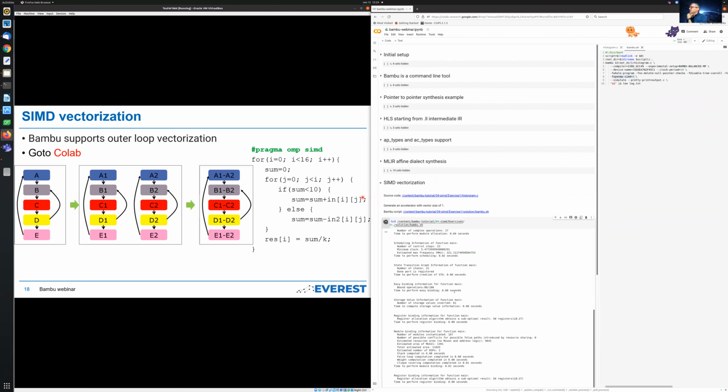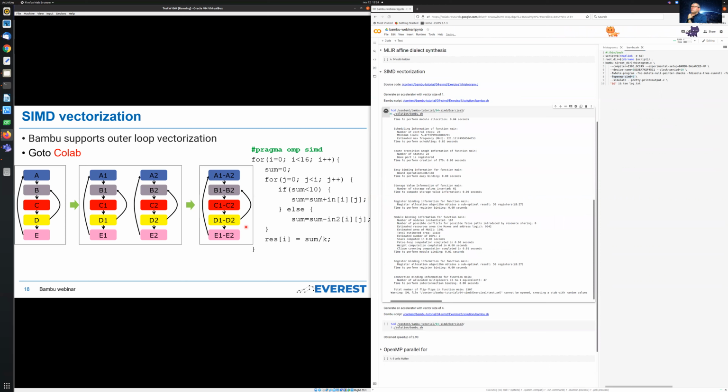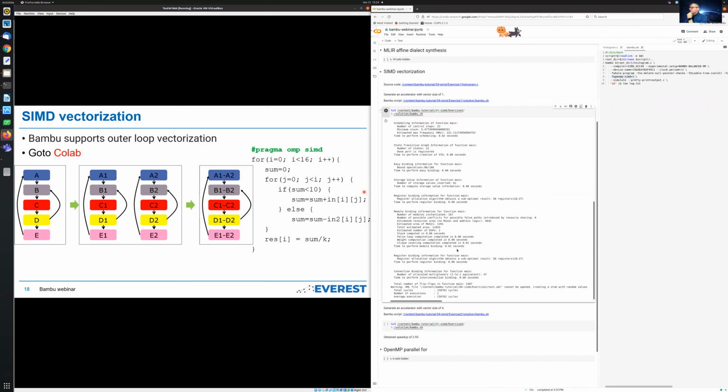And then we are going to parallelize the outer loop 4 times. So we are actually overlapping 4 iterations of the loop. So the number of cycles is this one. So let's change the script a bit by putting a 4 here and run the example.